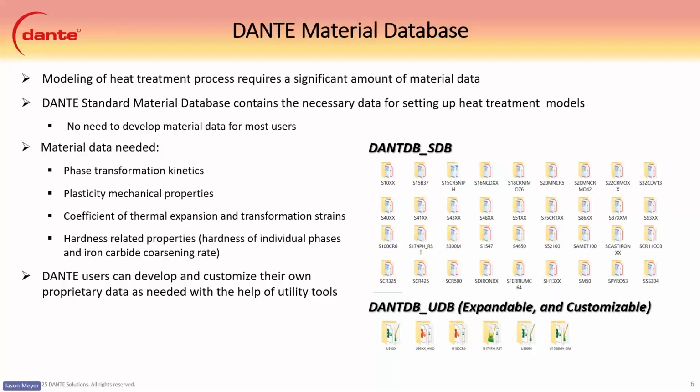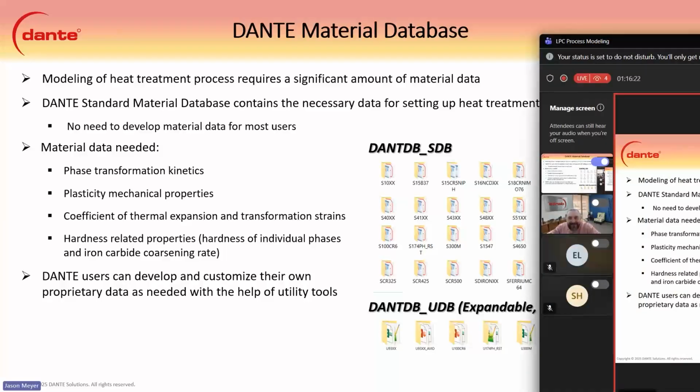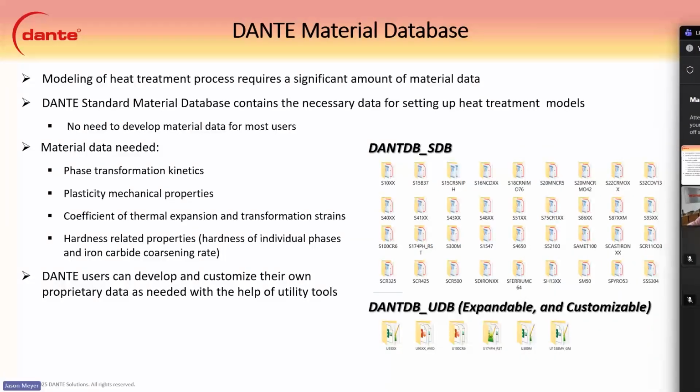Okay, that's a big one right here at the end. So we have which kinetics effects, especially in the carbide precipitation and austenite transformation. So this is basically if you would activate the carbon partitioning or something in the thermal model, and the effect on that austenitizing is handled through the Dante database here for the transformation. And I don't think the carbon partitioning model includes the additional precipitation and diffusion that way.